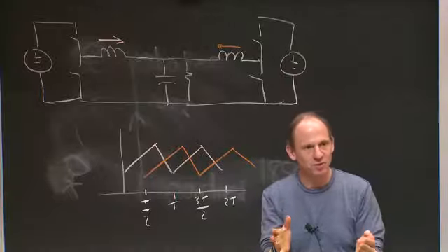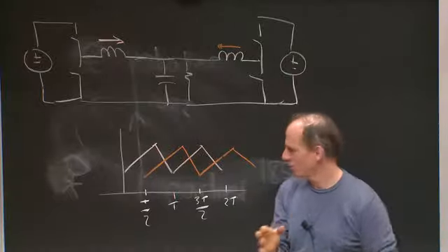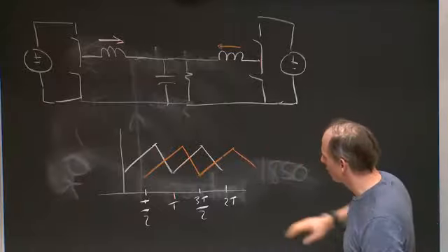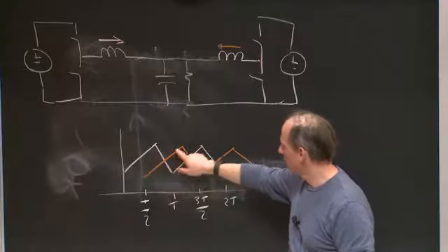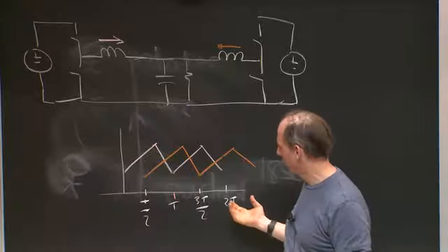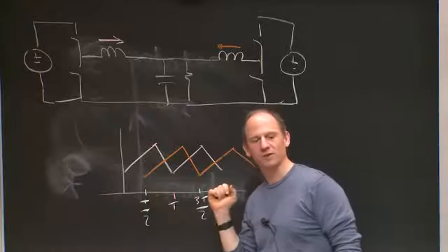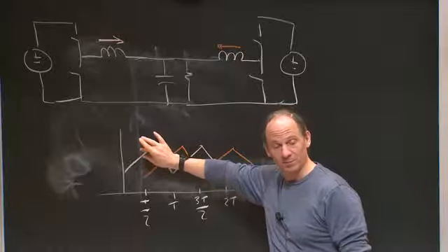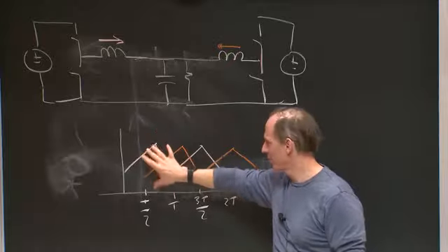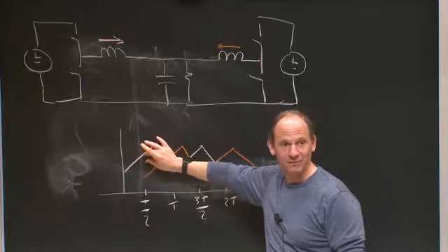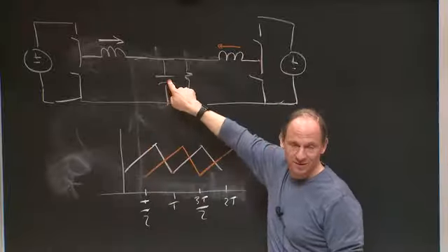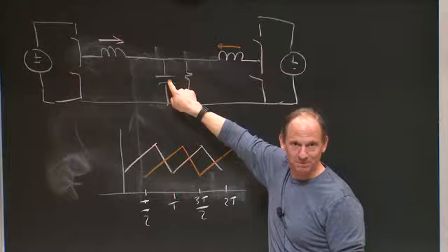So the fundamentals will cancel, the second harmonics will reinforce, and the net ripple, I'm not even going to try to draw it here, would basically have a fundamental at twice the switching frequency, right? So I get something that's both smaller amplitude, and you can show that the amplitude will be at most half, and twice the frequency, which makes it 4 times as easy for that capacitor to filter it.